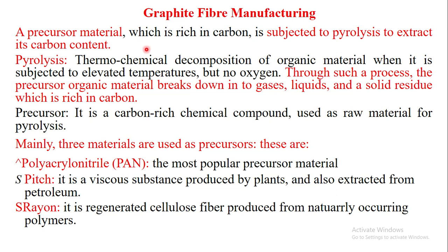Precursor material, which is rich in carbon, is subjected to pyrolysis to extract its carbon. Pyrolysis means the process of removing or extracting carbon from the materials. Pyrolysis is the thermochemical decomposition of organic materials when subjected to elevated temperatures but no oxygen.